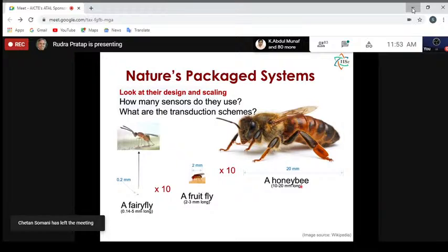That will be really dangerous. It should detonate only if it is fired and it hits a target at that speed. Then the deceleration will be huge, and that deceleration is what it should sense as a threshold deceleration or negative acceleration, and then engage the switch to detonate it. So these are also transducers of that nature.